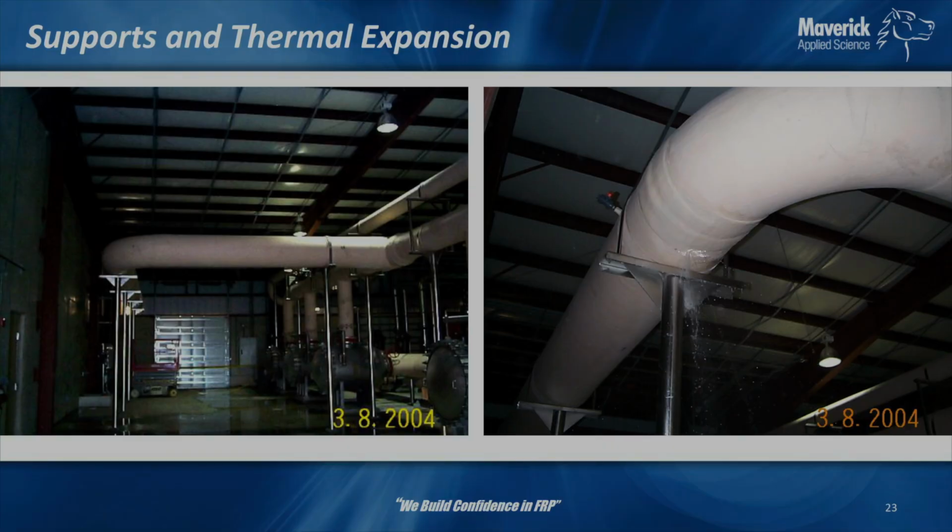But stiffness in structures matters as well, because you do have all those pressure loads, thermal loads, all of that. So this is some of the result that they saw here, and you can expect that with thermal load, if there's a failure, more times than not, it's going to be at a joint. I mean, the pipe's well made. It's the most controlled part of the manufacturing process.